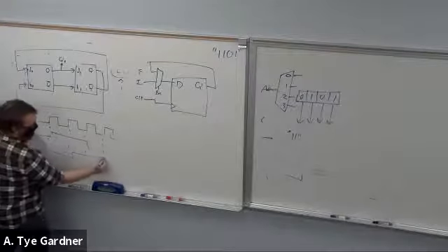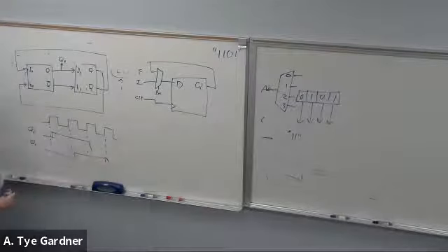And it goes 1, 2, 4 dropping. That's all. It's every 2 clock cycles it changes. And that's why I tried to emphasize this slight delay, right? Because if you didn't draw the slight delay, it gets really hard to tell what the inputs are when this rising edge happens.